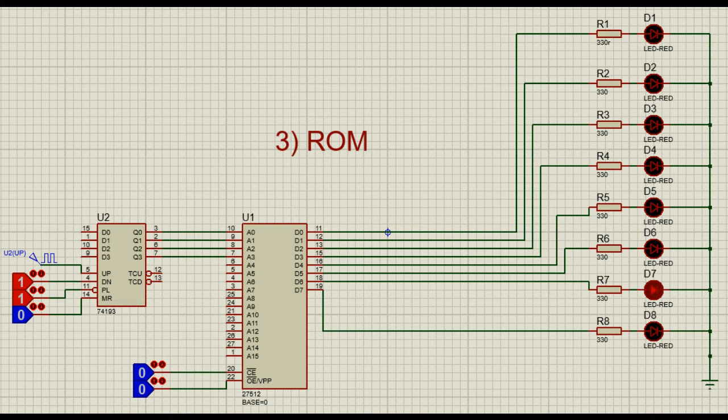The address bus can access address lines inside the ROM chip. Because the counter can only count from 0 to 15 in binary, it can only access 16 address lines inside the ROM chip. Moving to the right of the ROM chip, D0 to D7 is our data lines, or data bus. This executes the internal data for display. Following our data lines, each will be connected to a 330 ohm resistor along with an LED. The LEDs will display the sequence, all of which are connected to ground.